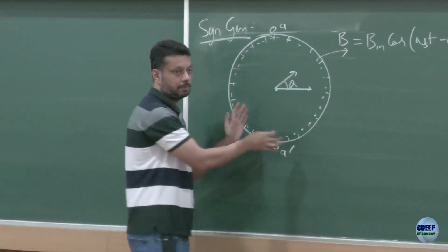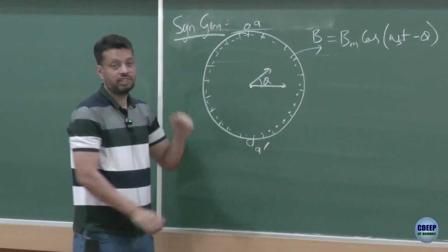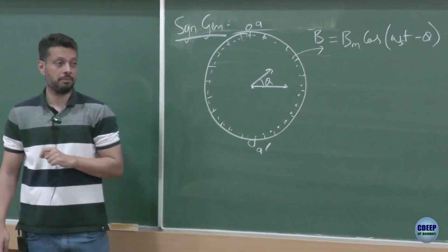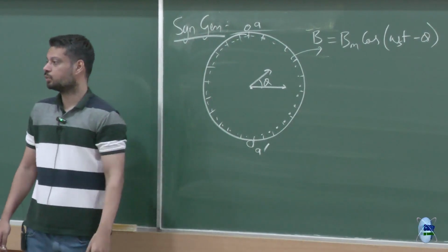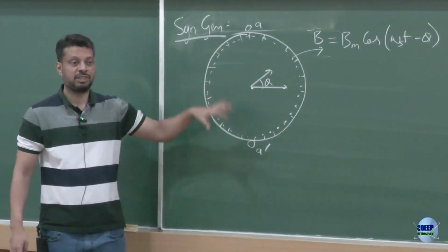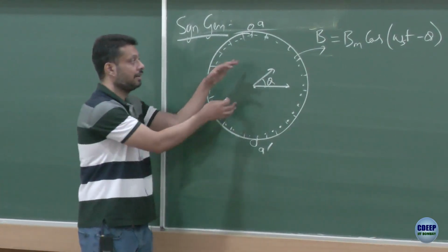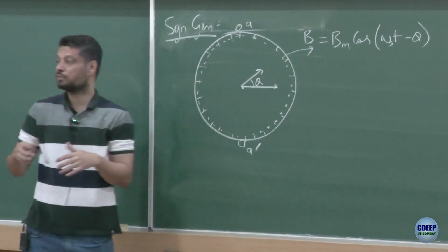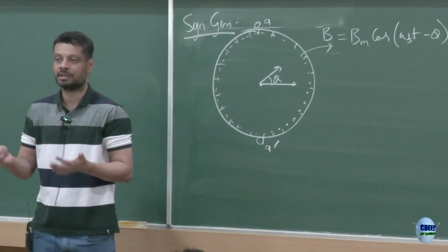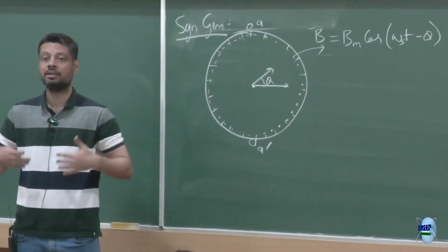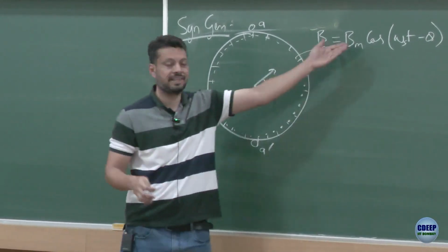So if all of you accept this, then the next step, as we did in other cases, is to find the voltage induced in this turn A prime. And similarly, you will have B phase winding, C phase winding, so we can also derive the voltage induced in those windings. These are stator. So the stator is what actually delivers power to the load. In this case, the rotor has, so to say, the field winding, and the stator has, so to say, the armature winding, because the stator is the one which is powering up the loads, which is feeding the load, and the rotor is the one which is creating the field. Rotor is the one which has created this field.